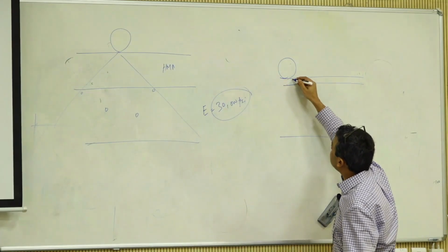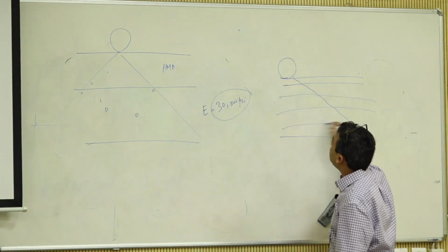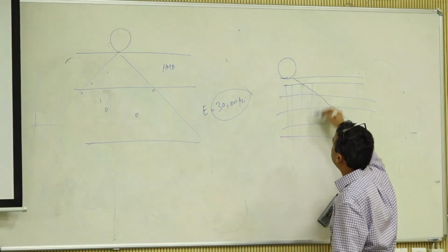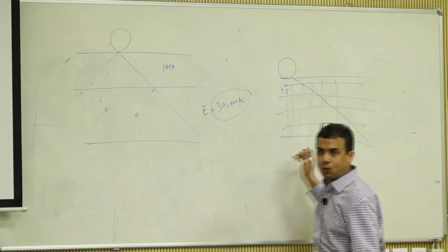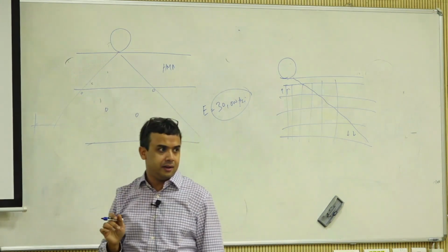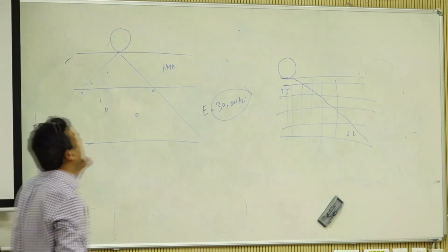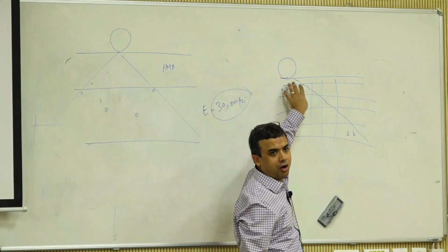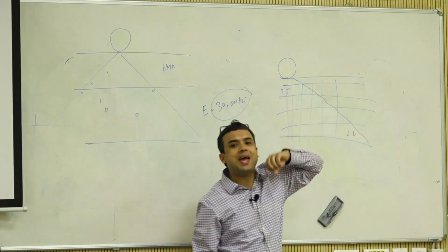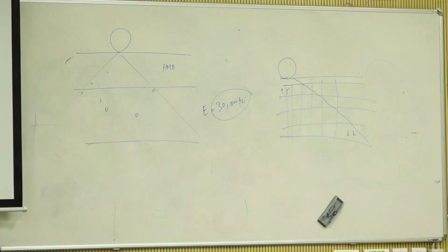So if you see, the stress actually keeps decreasing over here. If you plot the resilient modulus heat map or resilient modulus contours, you will see that this is very high numbers, versus as you go down it is very low numbers, right? So if you do that, now you are calculating your response. If you assume just one modulus value, at certain points you are underestimating the modulus, and at certain points you're way overestimating the modulus, right? So you have to reflect that.